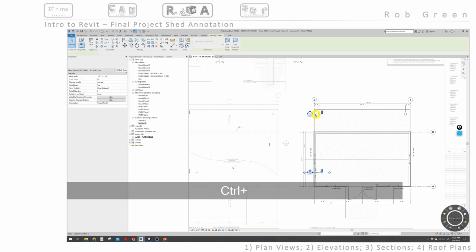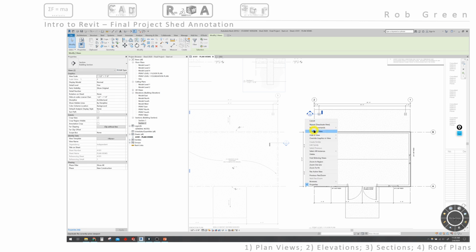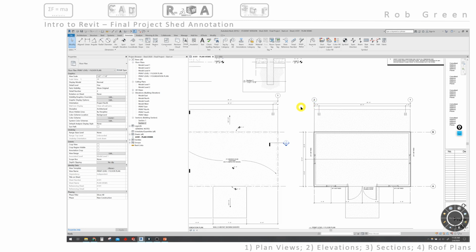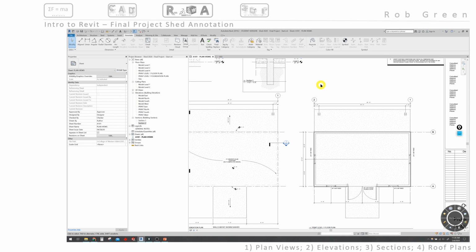And notice I'm doing this relatively soon after I've created the section views. My perspective is, for organization, it's important to create a view, use the view, browse the project, and delete the callouts. Hide the callouts in unwanted views relatively soon. Again, it's always helpful to keep my views clear and clean on a project.